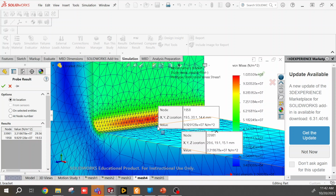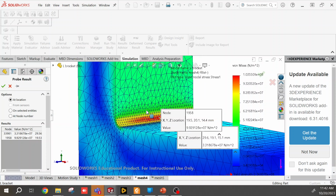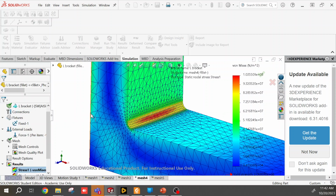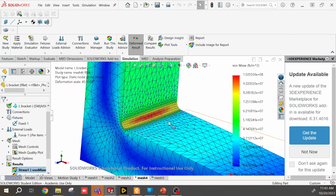The reason this didn't change very much is that the only place where changing the mesh density would have an effect is when there's a high gradient of something. Okay, meaning that there's a high rate of change. The difference between the stress here and here is next to nothing. So if we join all of these elements into one big element, it still would be technically nothing. But if we put more elements here, we're going to capture the gradients of stress a lot better. And so that's something you need to keep in mind in the back of your head all the time.